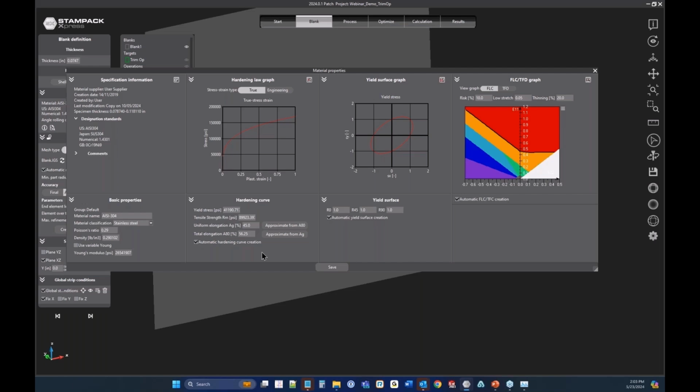The thickest part we ever simulated was 18 millimeters, and the standard stuff goes up to 8 or 10 millimeters, which is everyday business. As for part size, the part for the watch was 0.5 millimeter large, and the biggest part I ever saw on the screen was, I think, 5 meters. So in the end, it's all metal stamping. It doesn't matter.